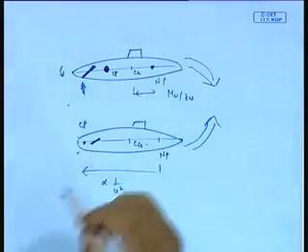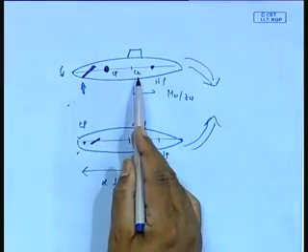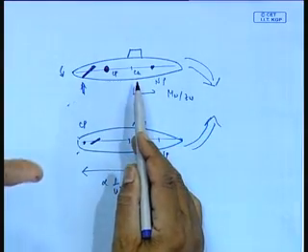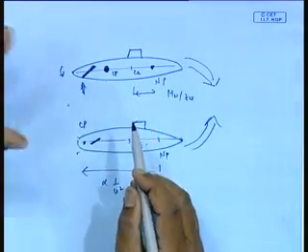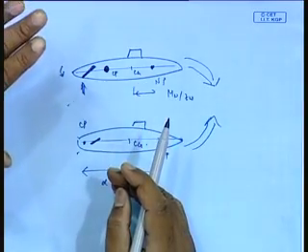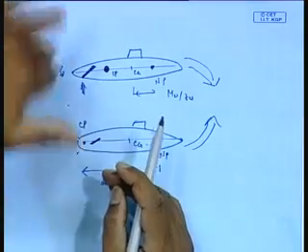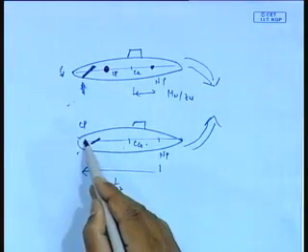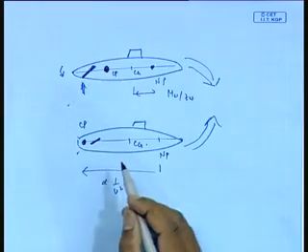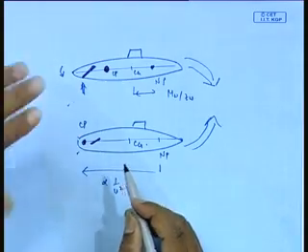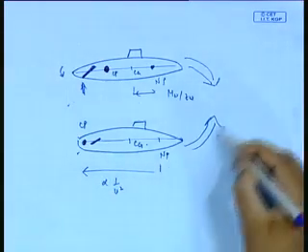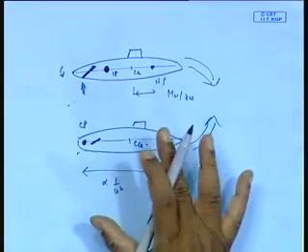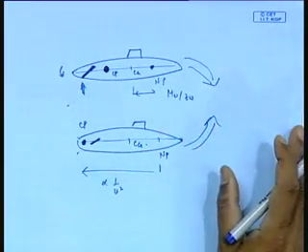But now, let us say you are the helmsman, and bringing the stern plane down is dive. But at lower speed, now you are going at 3 knots, Cp has turned out to be here. Now, I gave a dive down, and the vehicle begins to move up. This is what is called a reversal phenomenon, a very interesting phenomenon.